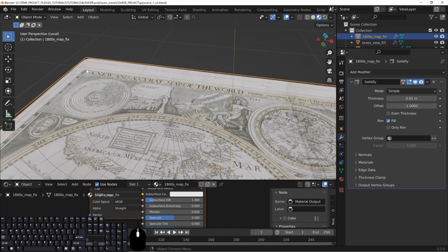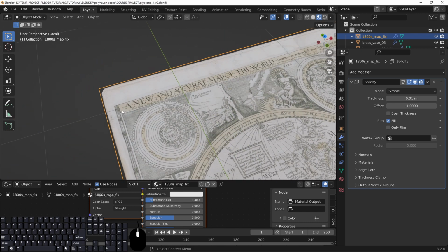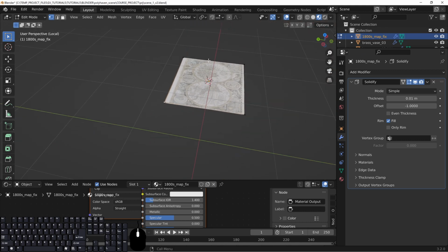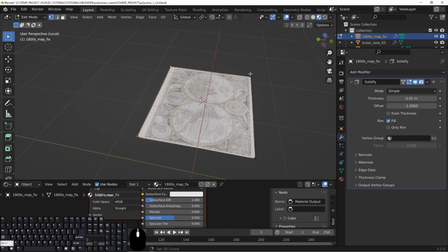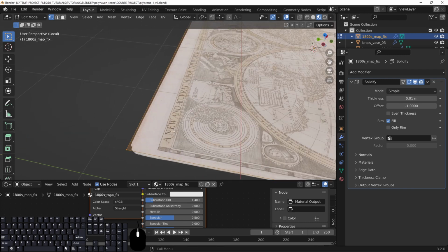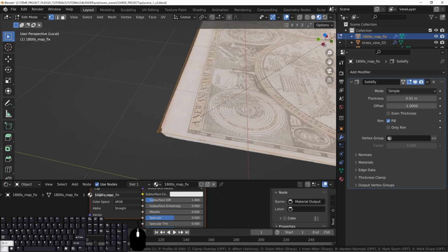So what you would need to do to make this work is go into edit mode, select all of these corners, Control Shift B, which will add a bevel to the edge. Do you see that? Let me just zoom in. Control Shift B will add a bevel to the edge if you drag it out like this. And you want to drag it in far enough to where it will actually take over those sides like that.